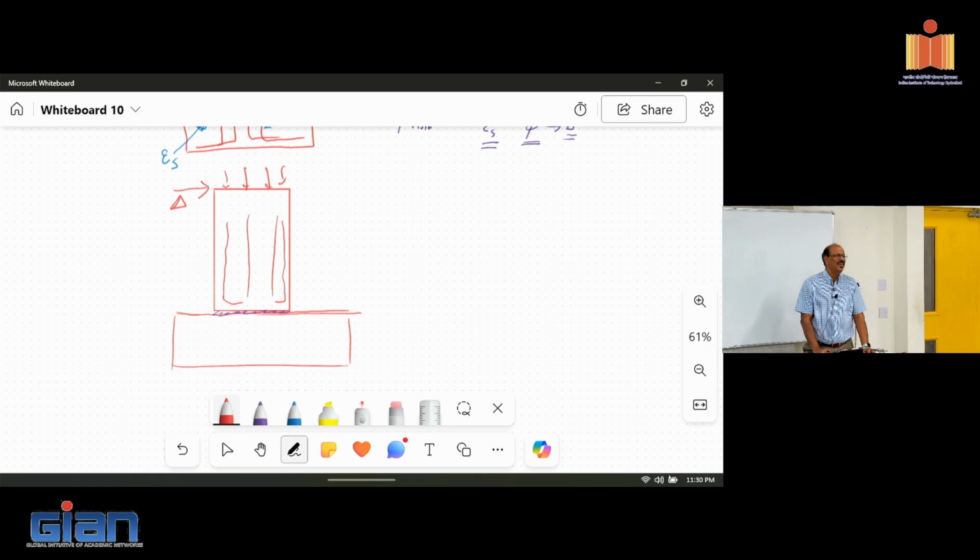Can you please repeat the question? So if it's a precast wall panel, and I put it with continuity using some kind of a grout pad only, with no reinforcement crossing between the two, but I want to push it with the displacement, and there are some gravity loads on the wall, my question is: what is the crack pattern and what is the force displacement going to look like?